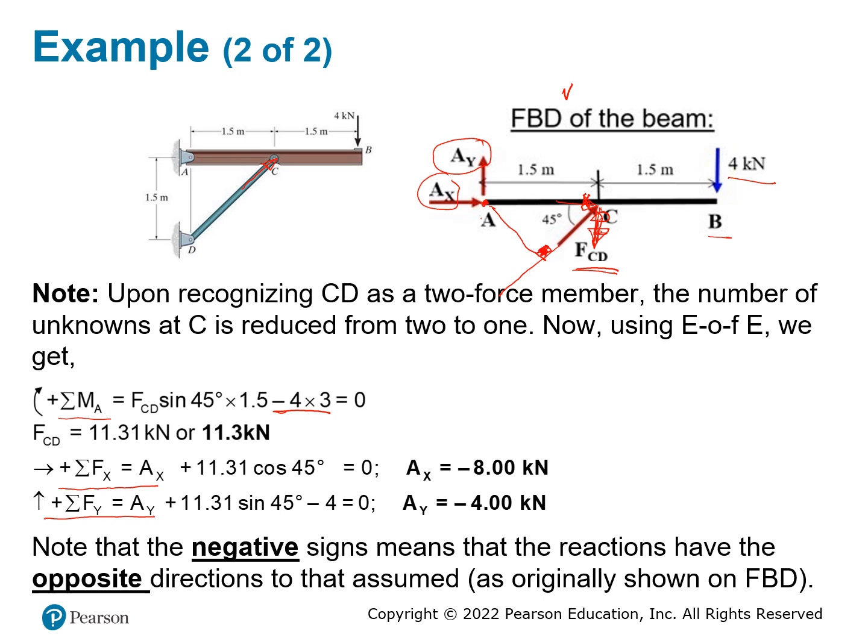And this is going to be 90 degrees. This will be 45 degrees. Right. And so if this one is 1.5, which is the hypotenuse, and this is the 45 degrees, you can use the law of sines. Or you can simply say, well, sine 45 degrees is going to be equal to cosine 45 degrees, because they are going to be the same. And it's going to be this distance divided by 1.5. Right, this is the lever arm.